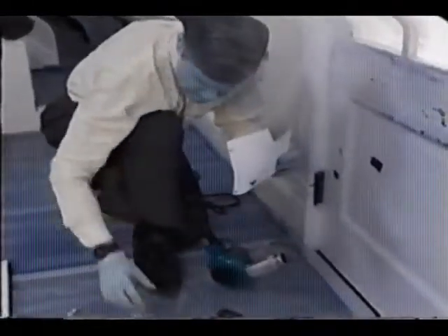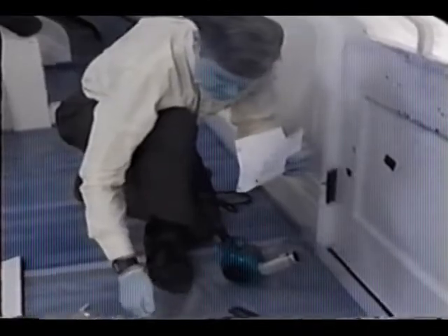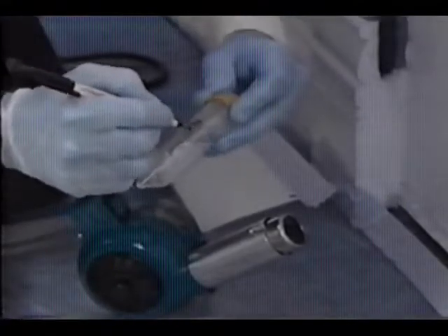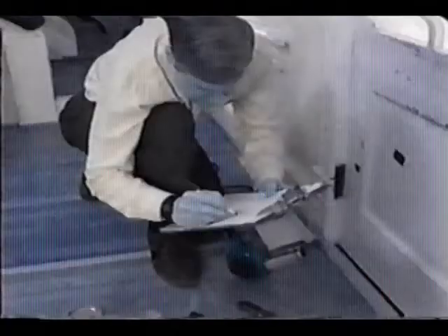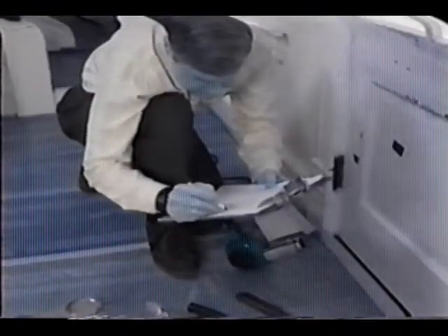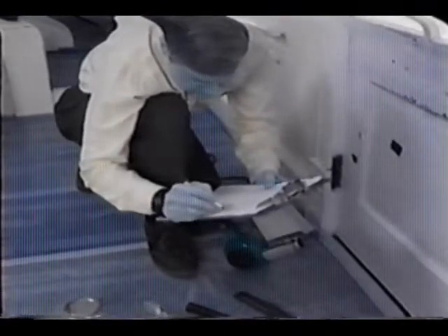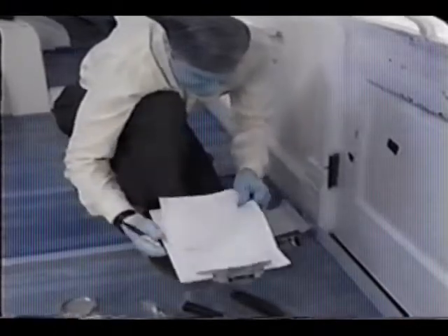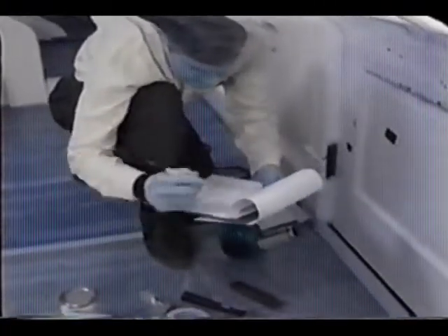Remove all of the layers of paint within that area and place the entire sample in a hard-shelled container. Attempt to remove all paint within the sample area. You must identify the sample with the sample number on the label. Record the sample number on a laboratory submittal form. Finally, record the sample number, the room location, and the component on the field sampling form.